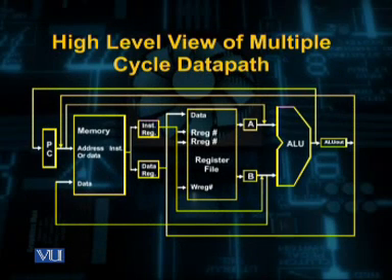New temporary registers, namely the instruction register, data memory operand registers A and B, and an ALU output register, are included to hold information for use in a later cycle. For example, memory read in cycle 4 is written in cycle 5 for the load instruction.